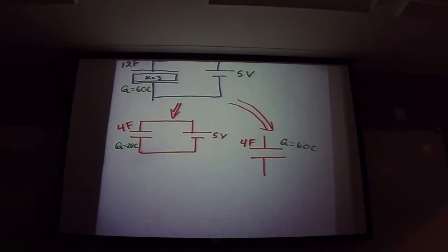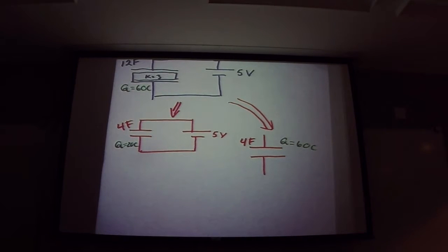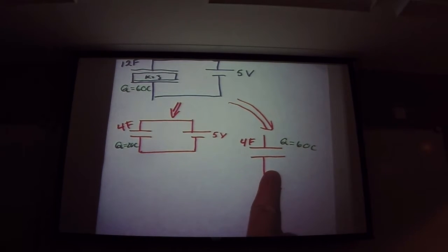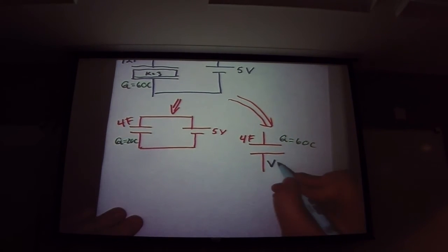And how does it hold on to that much of the charge when it's taking out the dielectric? Well, it has to. There's nowhere for it to go. The dielectric doesn't take any with it, because the dielectric is a polarized insulator. You're just pulling it out. So what's going to happen to the voltage across this thing? It's going to increase when you pull that thing out. The voltage here is not going to be 5 volts, it's going to be 15 volts.